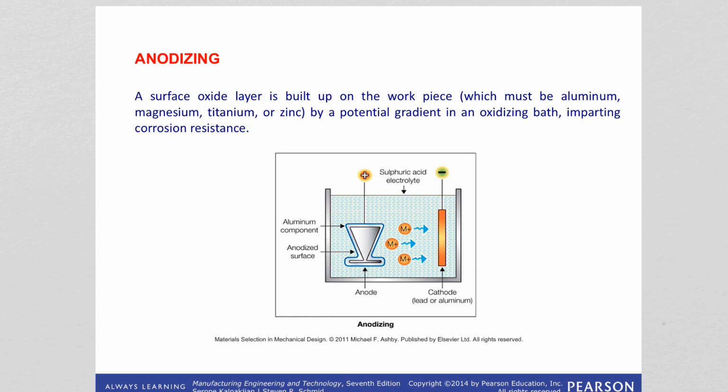So what is anodizing? Okay, so anodizing is basically an intentional oxidation process. If you want to form an oxide layer on top of a part, because we have learned that each oxide layer has its own characteristics, right? Chromium oxide provides protection against corrosion, or formation of aluminum oxide is again preventing corrosion of aluminum, but it is also a porous layer.